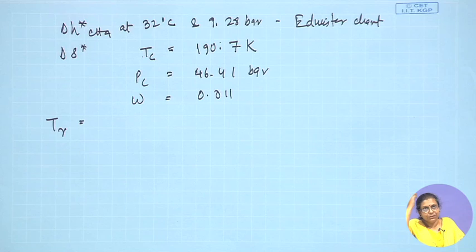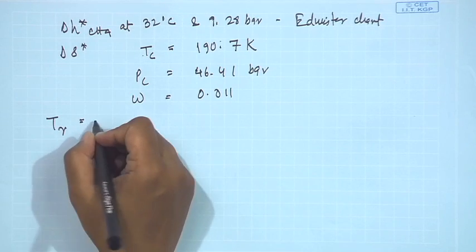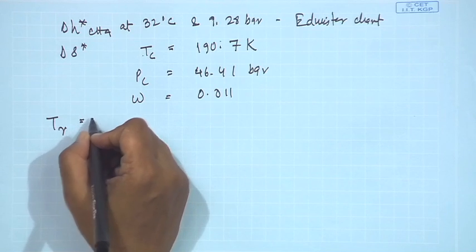Now there is one thing which I would like to tell: in problems you tend to make mistakes just because you do not consider the right units. It's very important when you are working with pressure. Suppose you are using Antoine's equation, very frequently the constants are given for torr, so the pressure which you are going to use has to be in torr. When you are working with temperatures, see in which unit they are given. These things are very important if you want to arrive at correct answers, not only for thermodynamics, for anything for that matter.